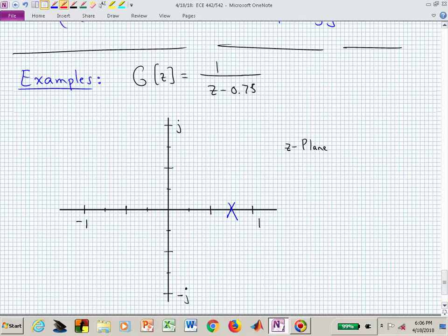You just want a gain. If you now have a gain in a closed loop system, what does that beg you to do with this z-plane plot? Root locus. Now all you have to do is sketch the root locus for this pole zero diagram, and that would give you all of the potential closed loop poles as you adjusted the gain from 0 to infinity.